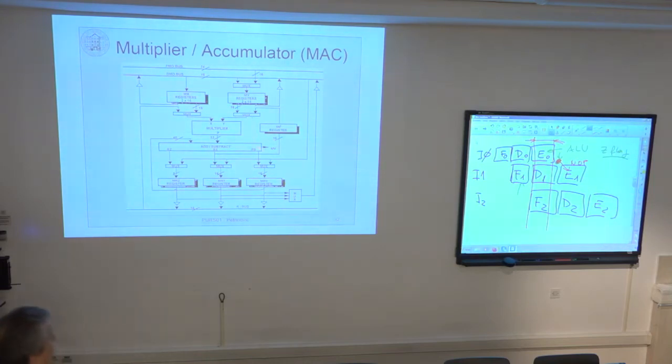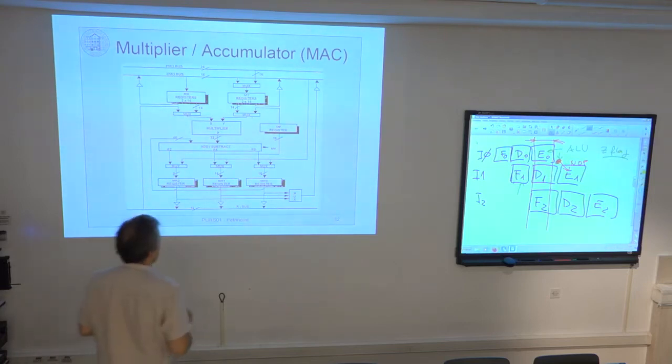So if I want to store the product into the feedback register, then the most significant part of the product, the upper 16 bits, is stored in the feedback register. And the lower 16 bits are discarded. Why do I say this? Because the default mode is fractional mode. So in the fractional mode, of course, the most significant part is in the upper word, and the lower word is less significant.